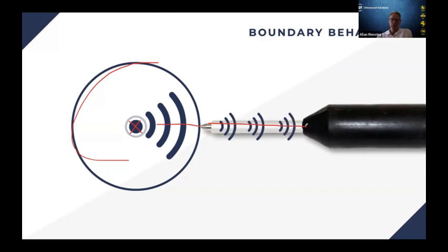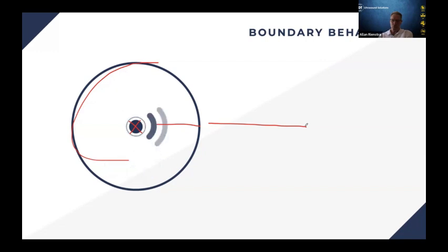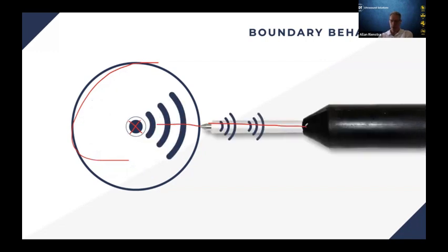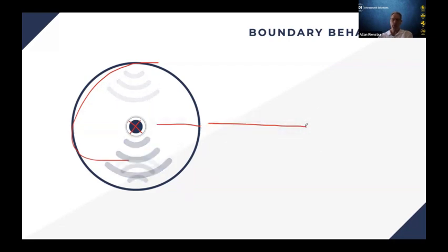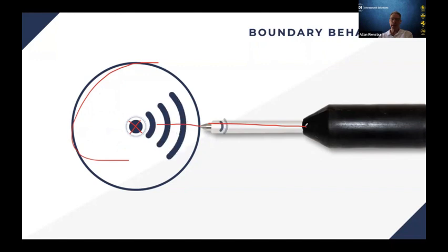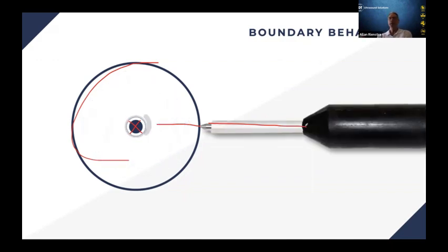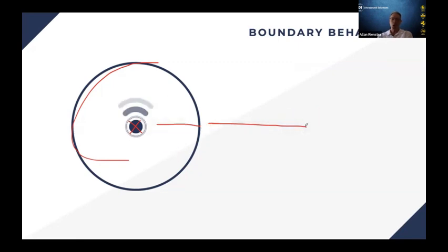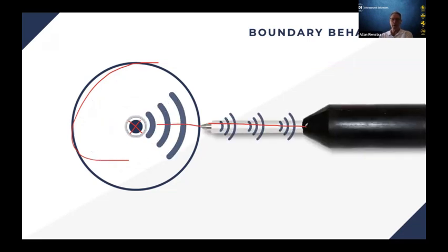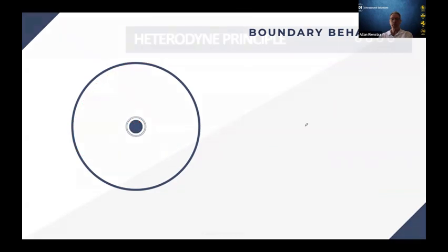Well, this is also beneficial for us because, for example, if we're trying to listen for arcing or corona discharge, partial discharge inside of an oil-filled transformer, the way we're going to hear that is to put an ultrasonic sensor on the body of the transformer and pull that ultrasound out, just the way a doctor might put a stethoscope on your chest to listen to your heart or your lungs. We're putting a stethoscope on the outside of the transformer or of the asset to hear what's going on inside